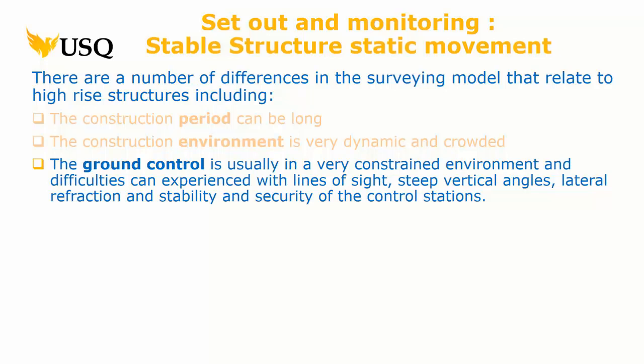You've got to be able to see the building. It quickly disappears as well, and it's also obstructed by things like cranes and by cladding. They put cladding up fairly quickly, or scaffolding. The scaffolders don't say, oh, I'll put it here so the surveyor can see through. They're not that friendly, right? So you've got to think about those lines of sight, and usually the solution is massive redundancy. Assume you're going to be blocked, right? So you've got to have more redundancy.